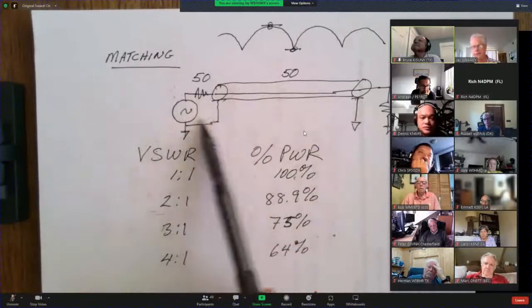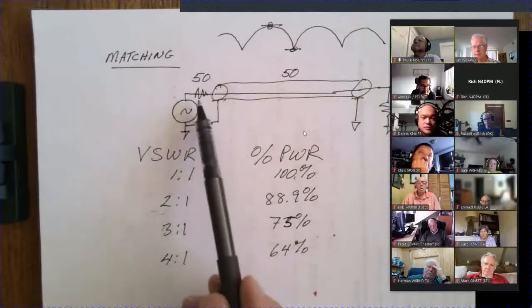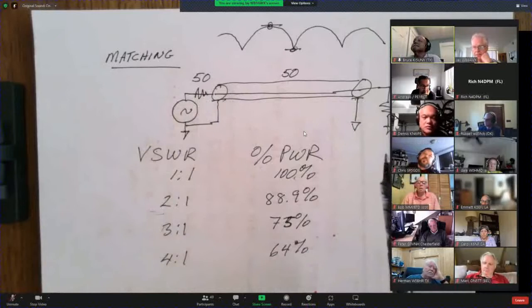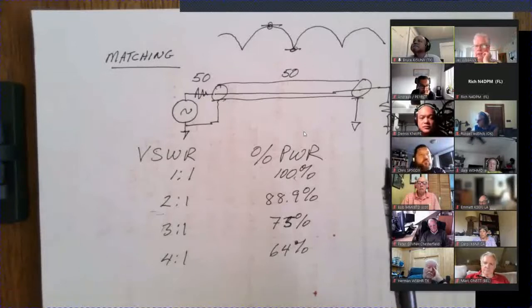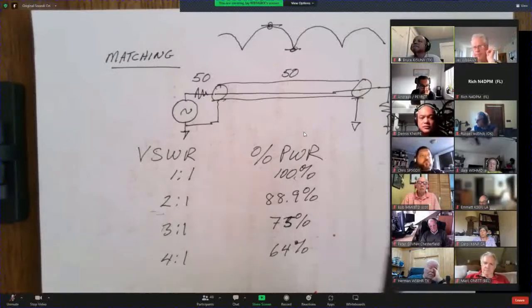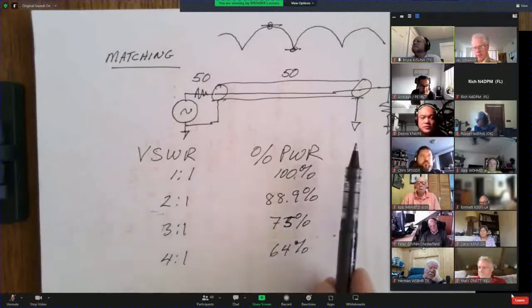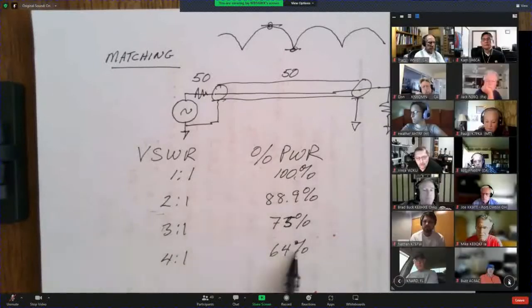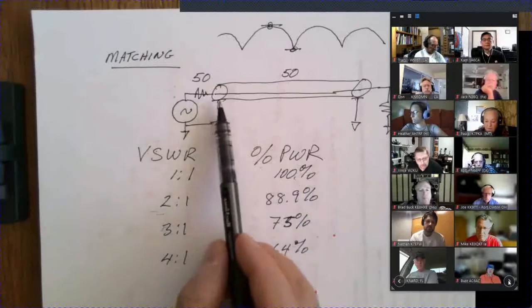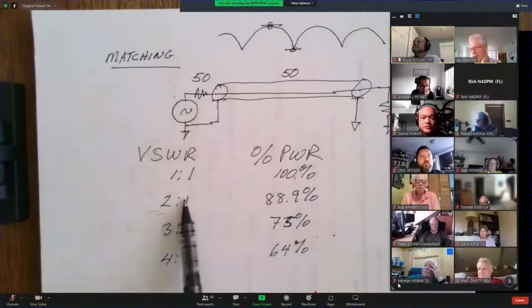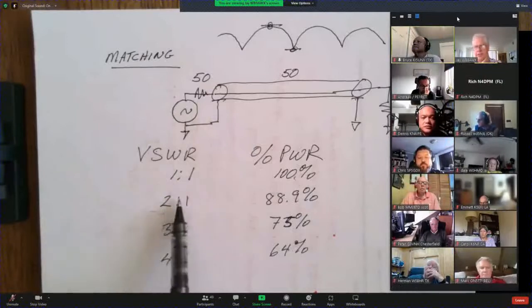Typically, the tuner is located in the transmitter these days. Actually, the best place for it is as close to the antenna as possible, but that's not always practical. You can't have a tuner floating up on your dipole that's 40 or 50 feet, or tens of meters, above the ground. So the key here is to remember that I would suggest you stay below 2 to 1.